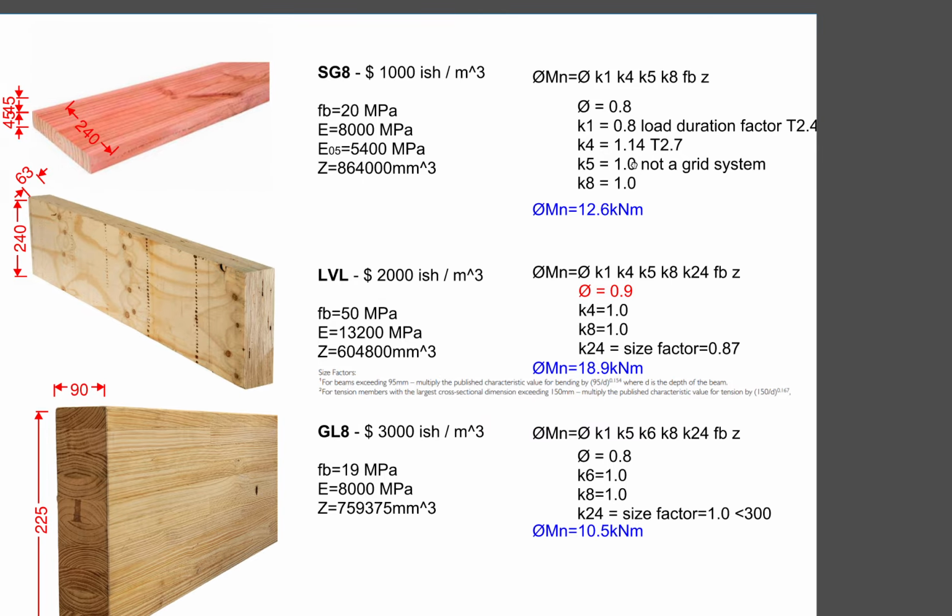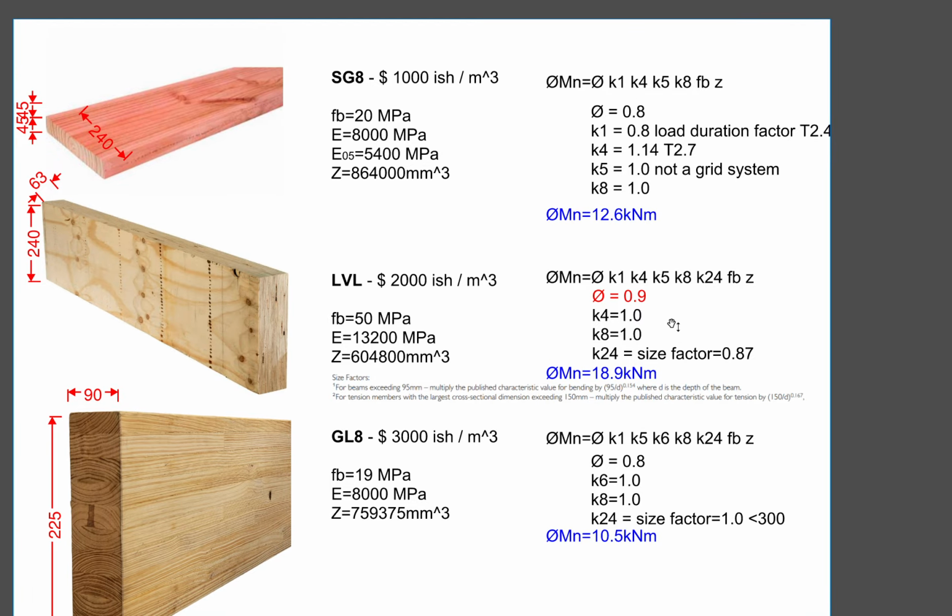So in terms of design of the bending strength, the formulas came out from the NZS 3603, and you can do it with 1720 if you like. It's the same thing. The only difference is these key factors. There are many key factors here. For me, I would just say this is a big K, and this big K comprises these small Ks: K1, K4, K5, K8, etc. Every design of the bending capacity, you would involve a material reduction factor, which is phi.